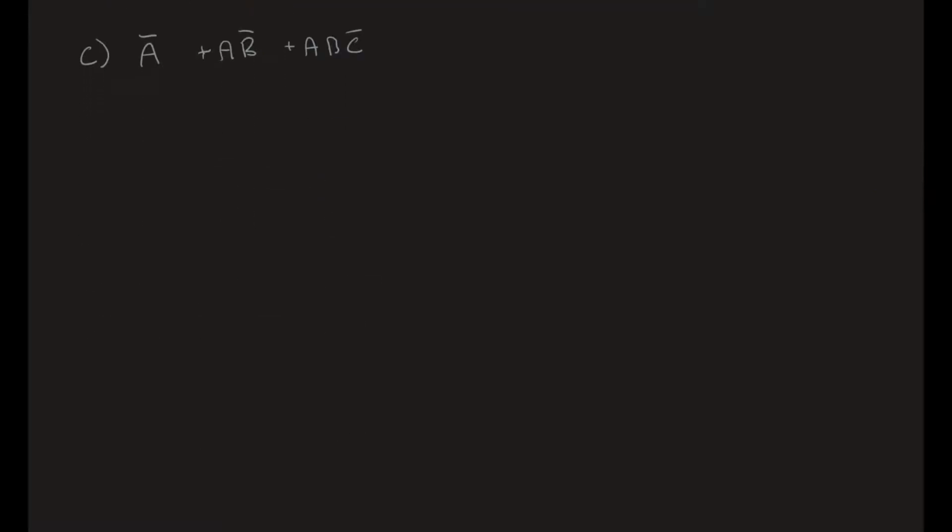Next. How about this one? Do we need a De Morgan? No. Is it in sum of products? Yes. Is it in standard sum of products? No. Fail, right? Notice that our first term is missing B and it's missing C. Our second term is missing C.